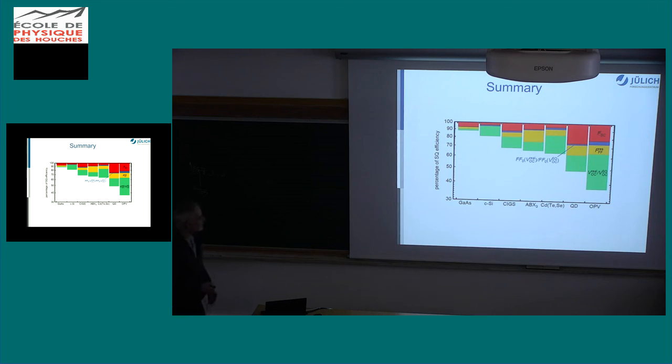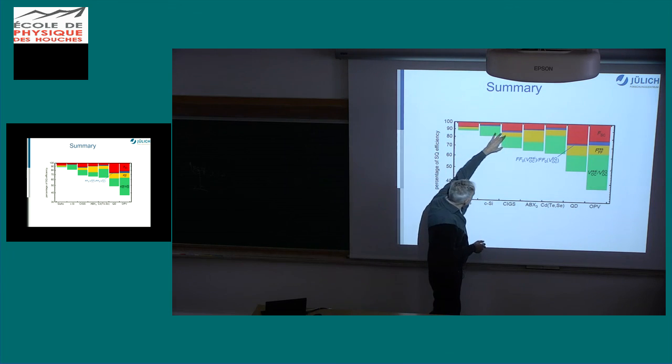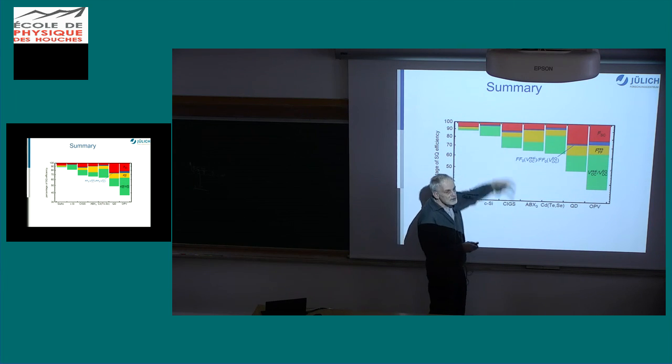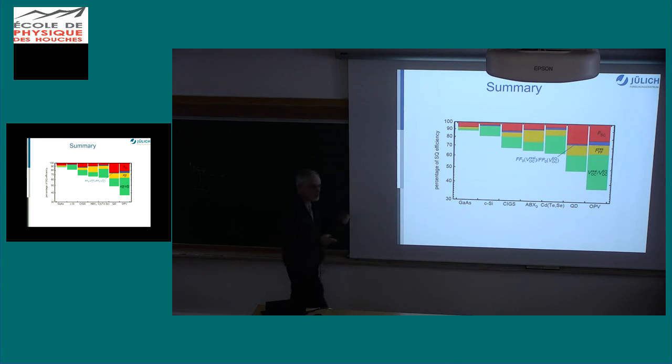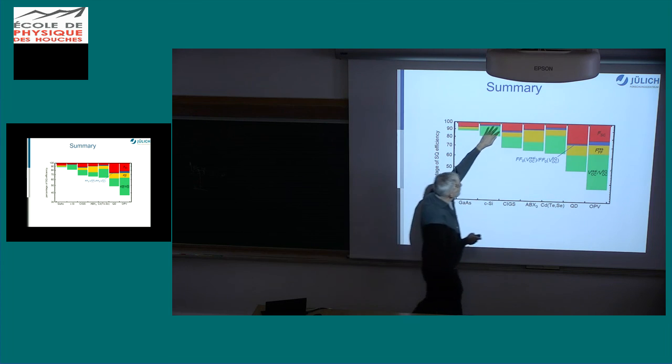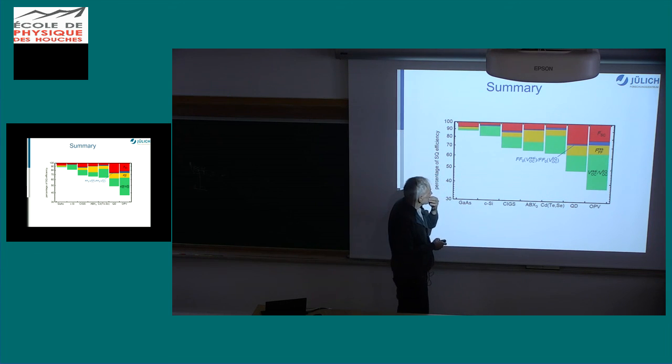Now, who is doing CIGS? I can give you some advice. CIGS is also doing very well for thin film solar cells, so it's still ahead of the perovskites, a little bit. There is a lot to do on non-radiative recombination, but there's also a lot to do on the JSC. Of course, we have this window. We have seen this in the quantum efficiency. There are a lot of losses with the window and buffer layer, so there's a lot to do here.